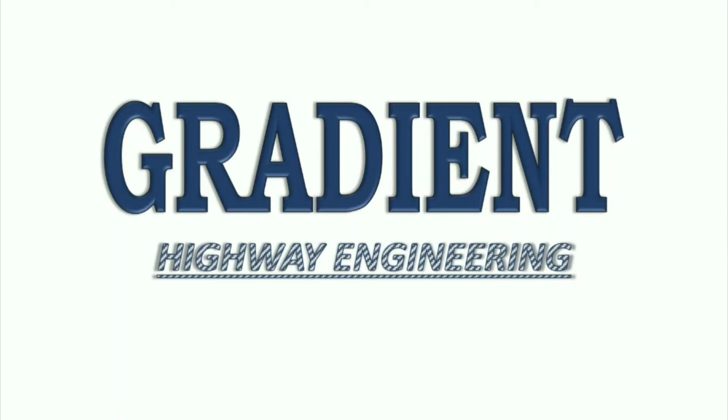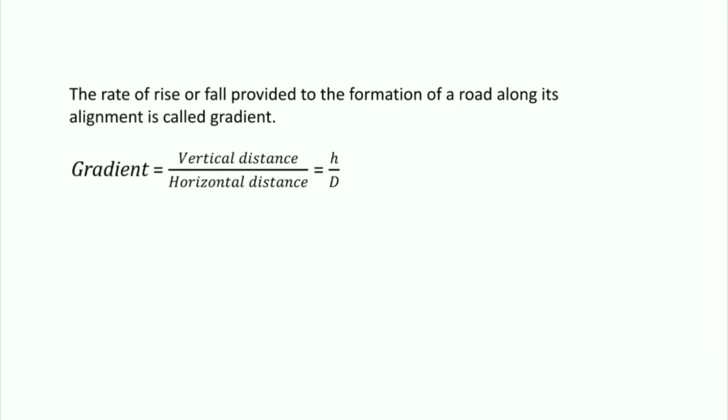Hello everyone, in this video we are discussing the gradient of roadway. Let's start. So what is gradient? The rate of rise or fall provided to the formation of a road along its alignment is known as gradient. So gradient is equal to vertical distance by horizontal distance, h by d.